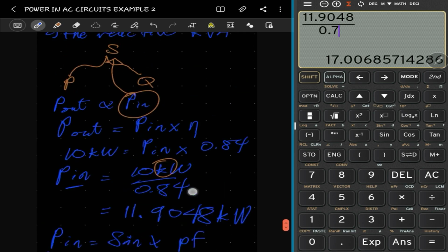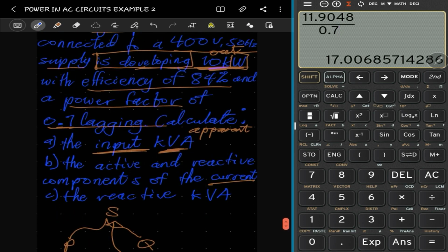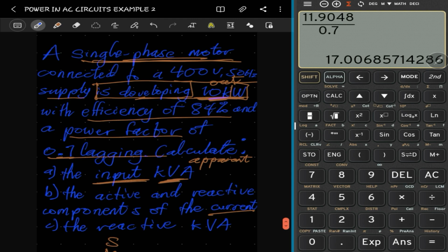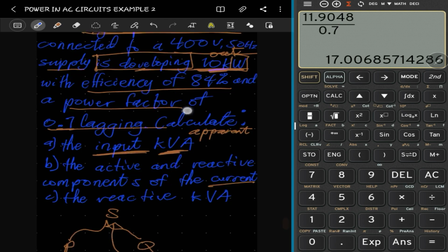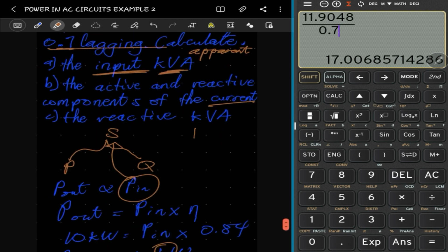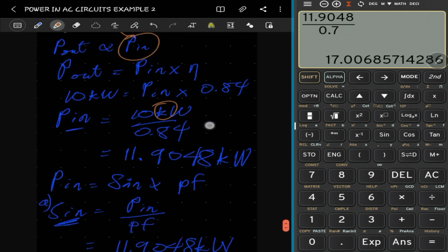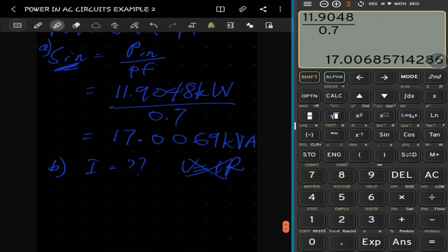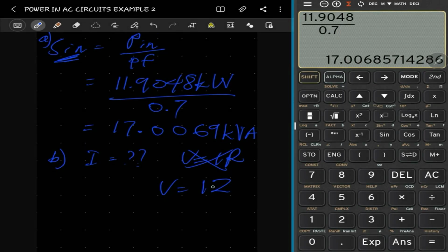Why? Because the circuit, let's see, it says power lagging here, meaning that we have some inductor component and some resistor component, right? That's what it says in terms of the power. Meaning you can't use this one directly, so you have to use V equal to IZ type. And neither can we use this, right? Why? Because we have the voltage, but we don't have the impedance, right?